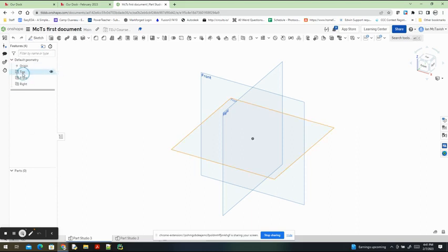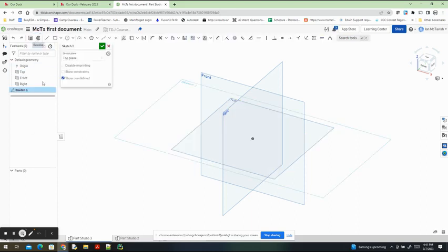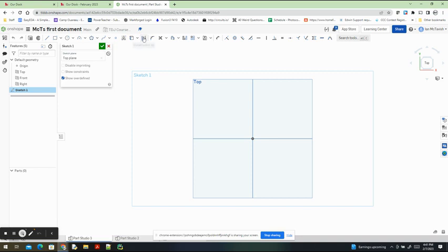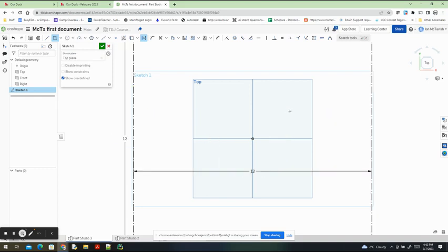So the first thing that we're going to do is create a sketch and use the top plane. So again, N to normalize the view. Now, Q will turn on the construction menu, and R turns on the center point rectangle. So we're going to create a center point rectangle of construction lines, and I'll show you what that does. So when you hold your mouse over the origin, click once, move your mouse, click, and this time you can set the size. So we're just going to use 12 inches by 12 inches.